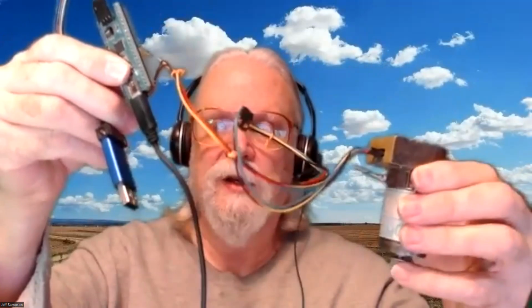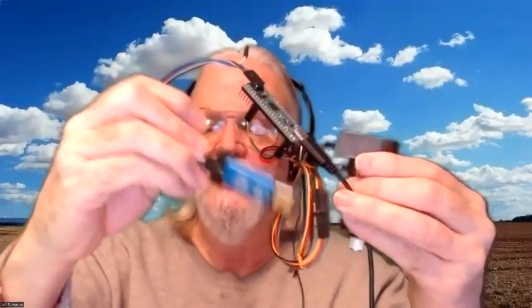And then the Black Pill board is set up basically the same way, where it's got the board and the debug module. Right now I've got this encoder plugged into it. It's actually a motor with an encoder on the back, but that gives me a convenient encoder. That's just plugged into the wires on that. To load it, I can either move that switch around, press reset, and tell Arduino to upload, and it'll do the DFU upload. Or if I've got this module plugged in, I just program it through that and make everybody happy.